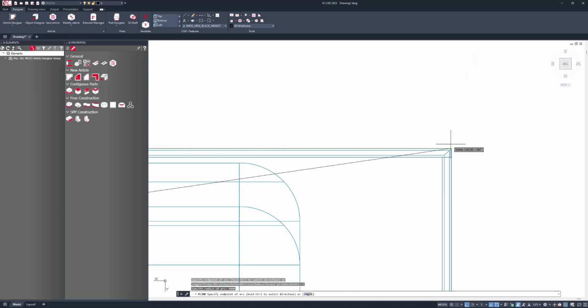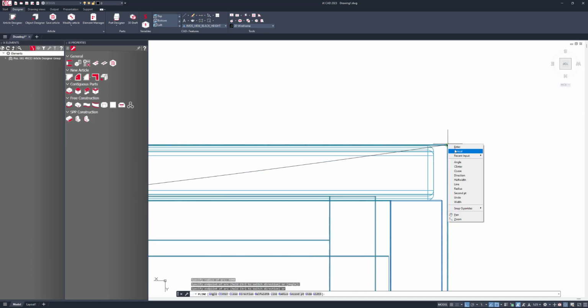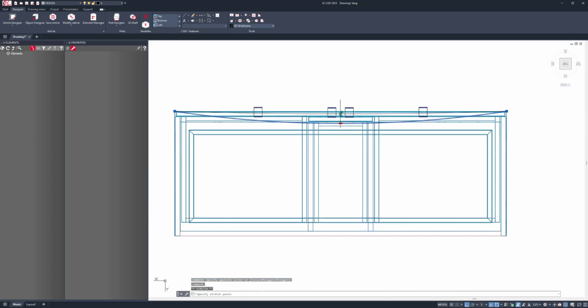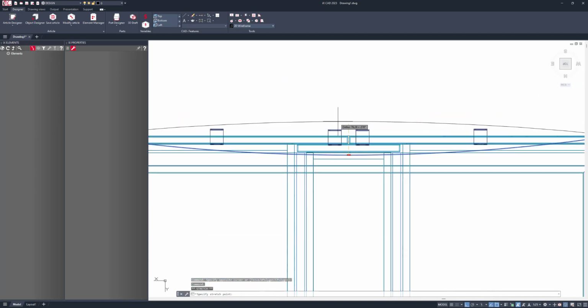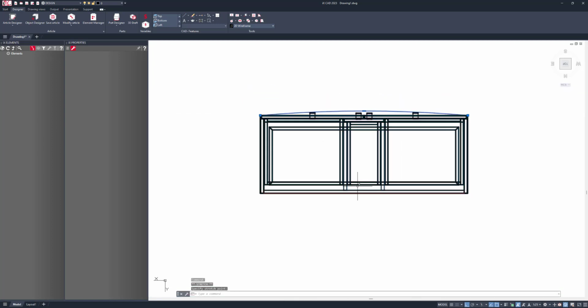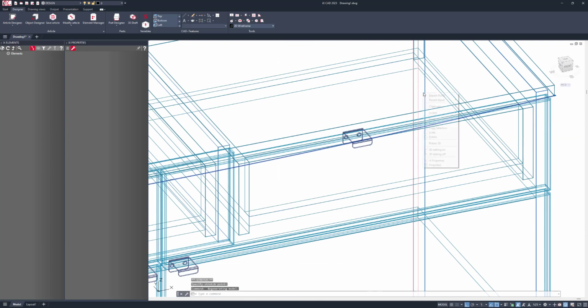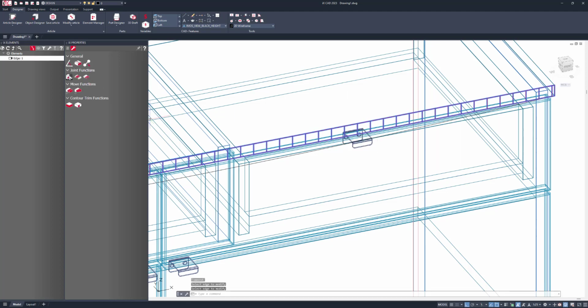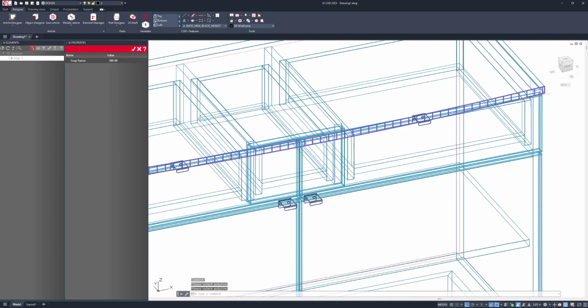And then I can snap this off. And I just want to pull that line just to clear those handles, just so that I don't catch my gene pocket on the handles. So let's pull that out. And now what I can do is say that that edge should snap to that line. So let's go and select the top edge of that worktop and say that that should follow my polyline.